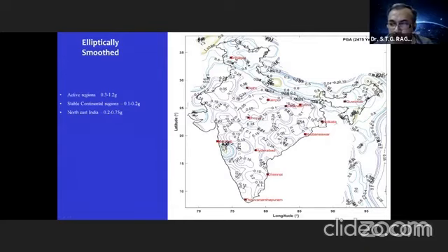Now, the main advantage of these maps is, if a person is in Guwahati, he will design for 0.5 G. If a person is in Chennai, he will design for some 0.12 G. The advantage is that on the whole of India, although the Z values are different, the risk level is the same. The risk of 1 by 2,500 is the reciprocal of this return period. So all over India, the risk level is the same, which means for insurance companies, the premium is uniform for our entire country, but design values are different. If you design for 0.12 G in Chennai, you are taking the same risk as a person designing in Guwahati with a design value of 0.5 G, so the risk levels are homogeneous. This is the advantage of these types of maps.